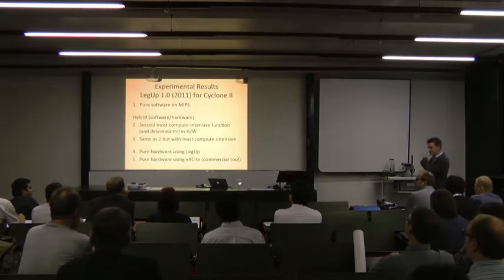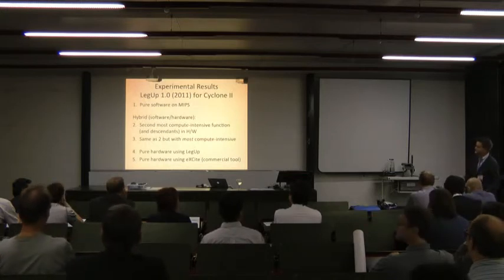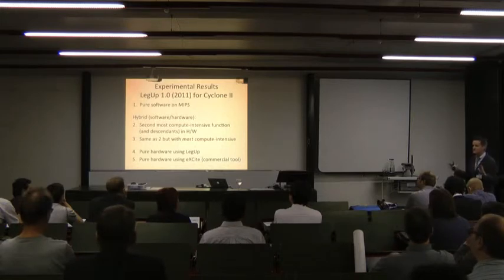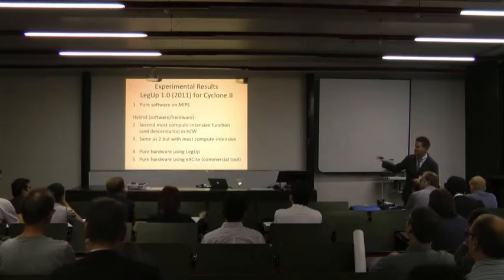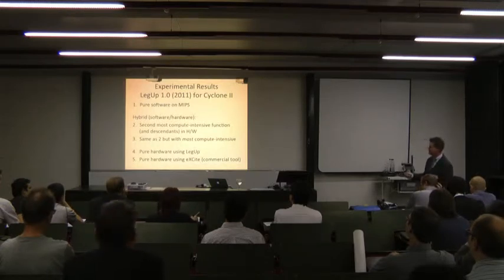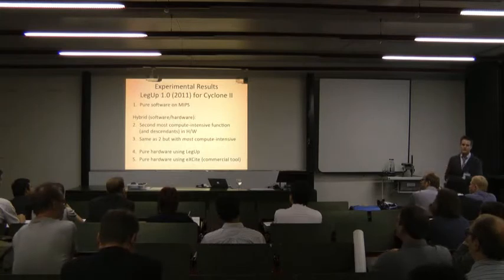Now, let me talk a bit about results, and then I'll go on to the kind of stuff that we're working on now. In our first release, which was 2011, we actually came up with several ways of evaluating it. We thought, first of all, we could take these benchmarks, we could run them in pure software on the MIPS, meaning to just forget about doing any high-level synthesis, pure software. Alternately, we could explore the software-hardware space. We could take some of each benchmark, we run it in software, some and run it in hardware. That's number 2. Number 3 was we run some in software, more in hardware. And number 4, we could take the entire benchmark, run it in pure hardware with LegUp.